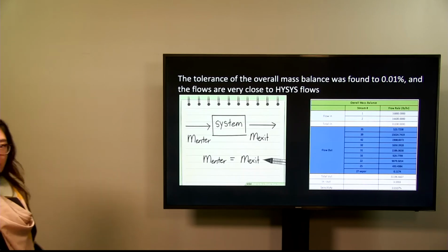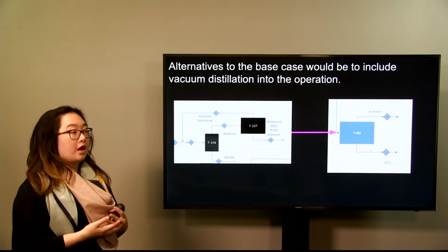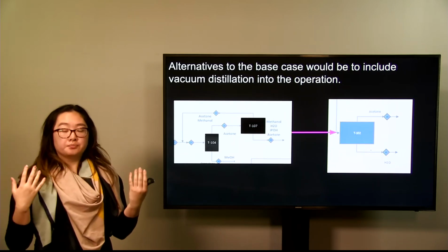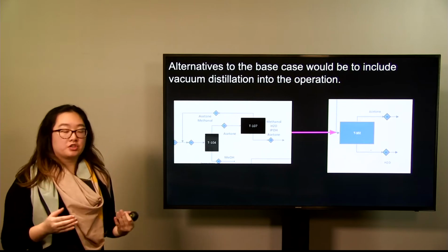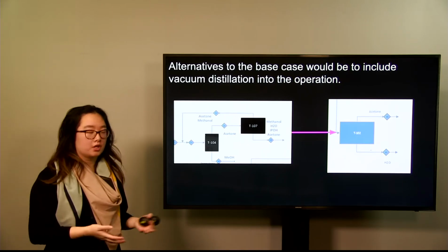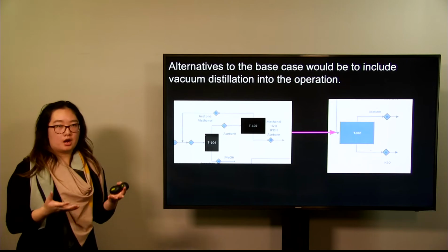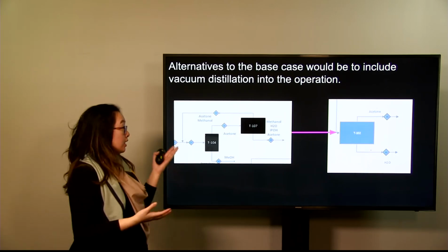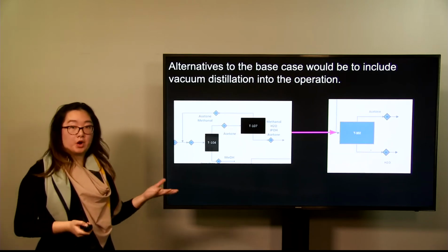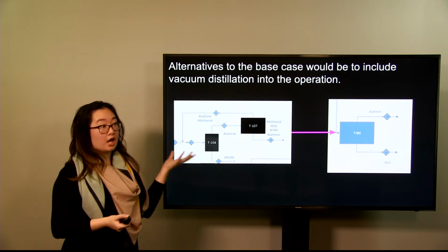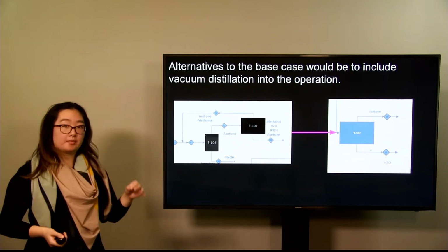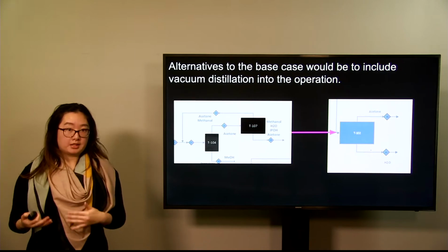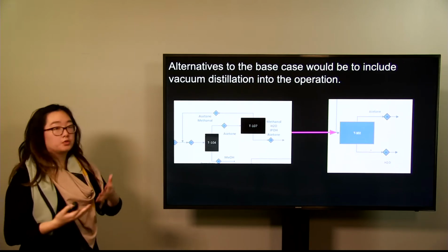As Saud said earlier, one of the main things that we based our initial estimations and design on is the boiling point differentials, by which we can separate things effectively. Now, that assumes that with the boiling point it separates at 100%. However, for the majority of our process, the acetone and methanol streams have been problematic as they form an azeotrope.